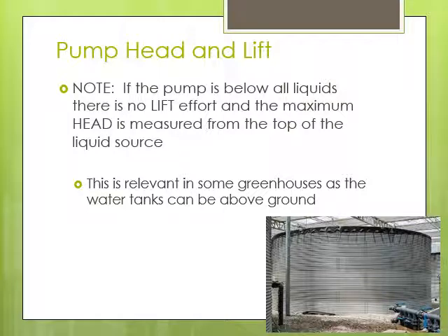So if the pump is below liquids, then lift is really not so much of an effort. So for example, in a greenhouse, we often have these large tanks that store water, fresh water and then nutrient filled water, and the pump would be located down below. But that means it doesn't have to suck water up. It just means it's going to be primed quickly with water and it has to push it out, and maybe a little higher than the height of the tank.